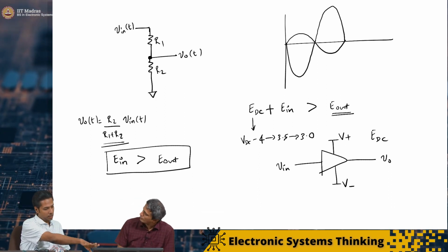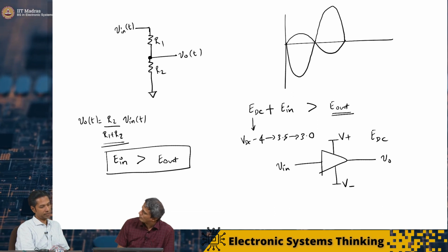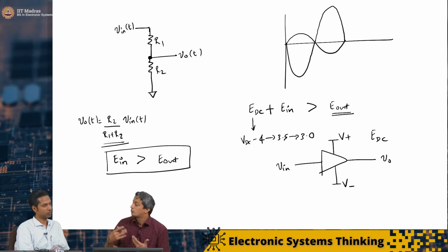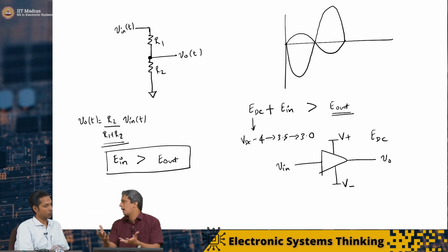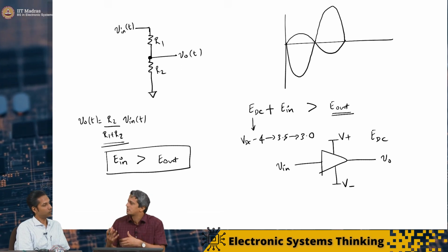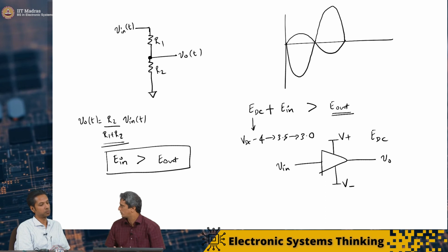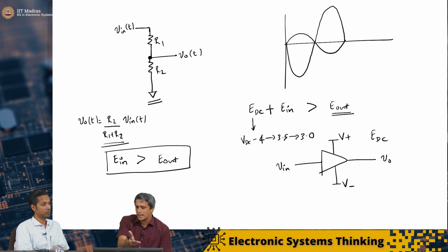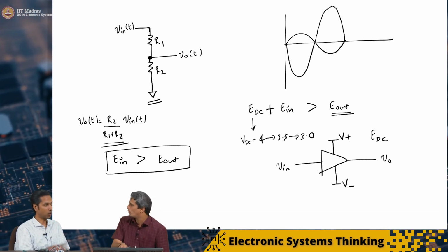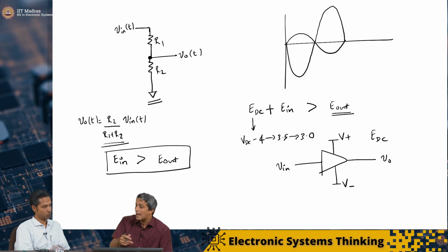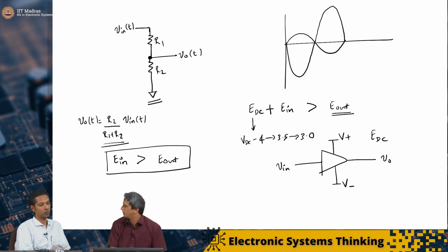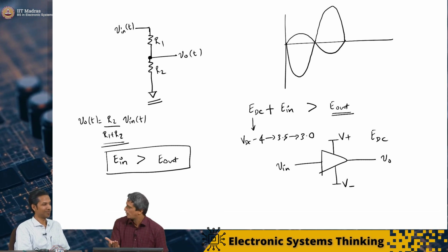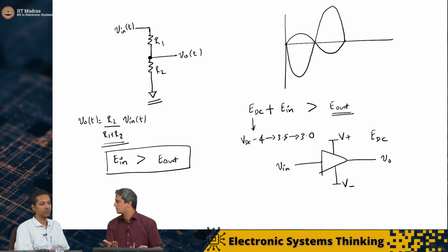So whenever there is an electronic amplifier like this, there is a power amplification also. It's not just voltage, it is the energy that is actually being amplified. And that energy is coming from some other supply source. Here, I did not need that extra source because I am taking it from the input and actually just scaling it down. I don't have to worry about adding energy to this particular system here, and therefore it was okay. R2 by R1 plus R2, as you said, is obviously a number less than 1. It has to be lesser energy, and therefore we were fine.